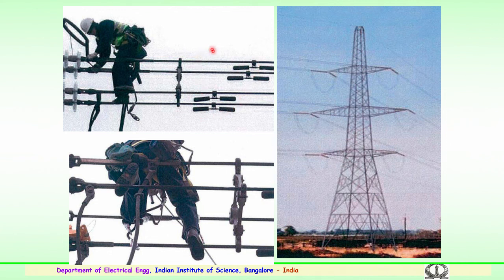So, in case of a 4 bundle conductor, there is a 4 bundle spacer, that is a quadruple spacer. Here you can see the quadruple spacer, similar to a square type of arrangement, with the distance maintained between conductors at typically 45 centimeters in case of India. So, a quadruple spacer is available and the dampers are connected to each of the conductors. This is how the conductor arrangements are made for EHV or UHV transmission near the tower ends. So, very important. The insulators are a very important component of a transmission system, conductors are much more important, and accessories and hardware, the tower and the foundations are equally important for UHV or EHV transmission.